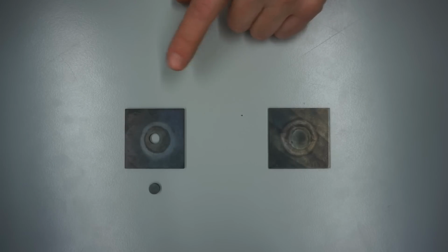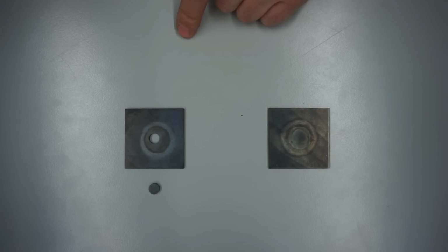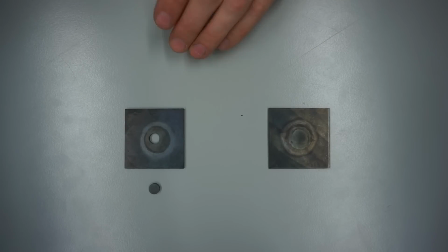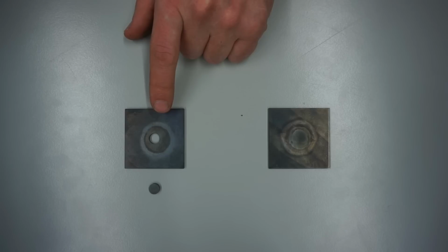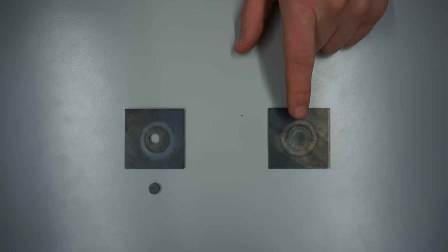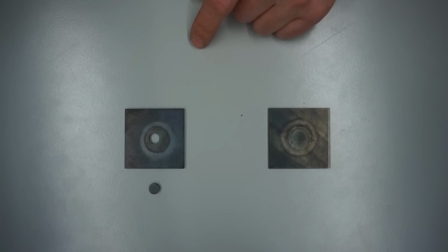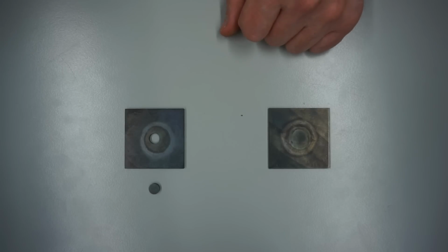But by comparing the two previous experiments, we can learn something about the elastic deformations due to residual stresses too. The two experiments are mechanically similar up to the moment when cooling begins. Then they start to differ because of a gap that develops between plug and sheet. Here, instead of a gap, radial stresses develop, where hot and cold zones interface.